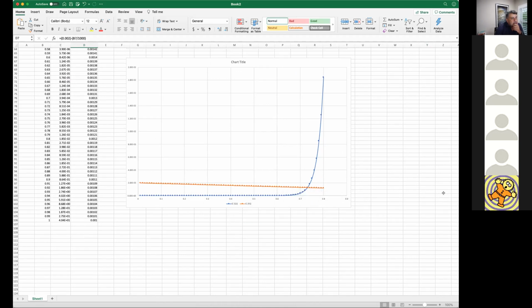And it's going to get to 0 somewhere out here in the graph. And it's going to 2 milliamps over here. So where these guys cross is around 0.73 volts for VBE and a collector current of 1.27 milliamps. And that's the only permissible place.